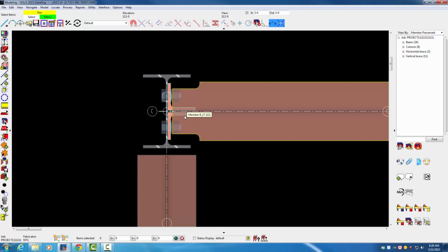As you look at sheet S3, this beam here is actually supposed to cantilever over the top of this column. Right now you can see the computer doesn't know that because we did not tell it. It's connecting this beam here into the column, but the connections failed. In our case, we want this beam to frame over the top of the column and run out to about here, which then will create this beam here to frame into this one.